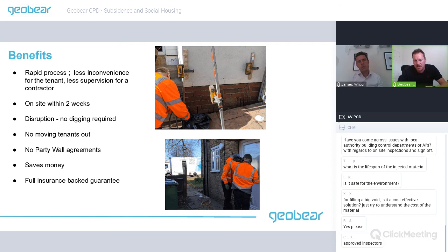We could use our material with clay lacquer, as mentioned earlier, as an option, but because the material's really suited to ground improvement jobs, it's not something we tend to use unless there's a structural need. There was a project in York where under one of the steps of the York Castle walls there's a big void, and they wanted to fill it with a structural fill to ensure that if there was any movement, it wouldn't come away from the building. So it really depends on a case by case basis, to be honest.